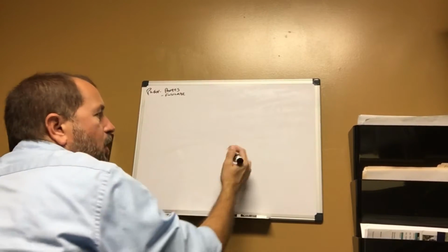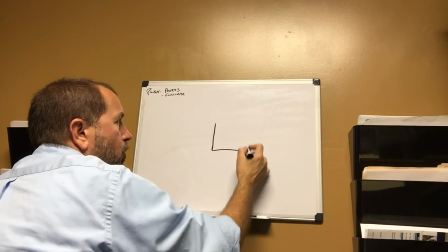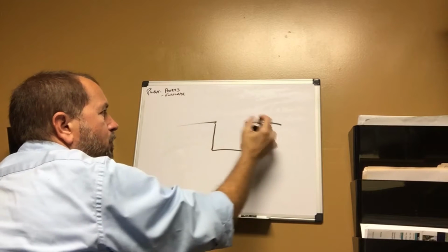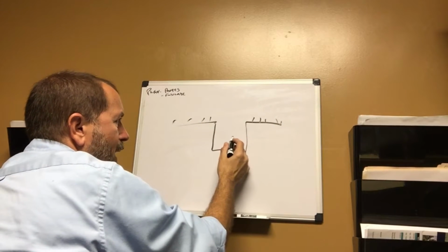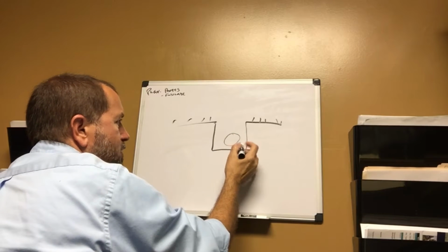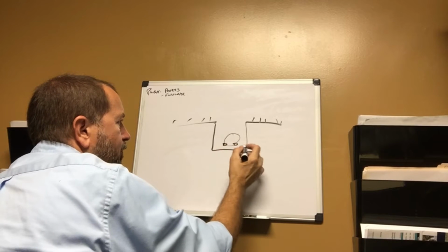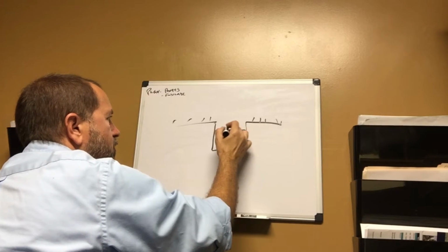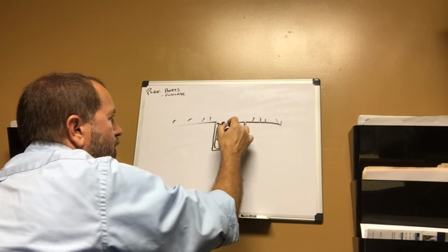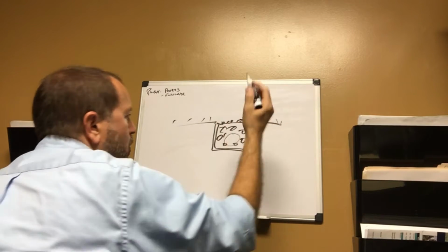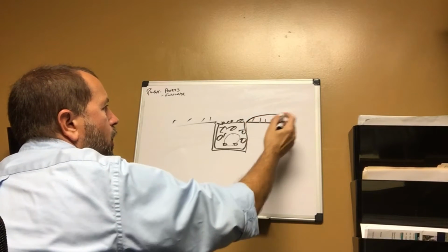A French drain is, we're digging this trench. We dig this trench in the ground like so. That's the ground. That's the grass. This is my hole. This is a pipe I put in the ground. The pipe has some holes in the bottom of it. And then I fill this thing up. It's all filled with rocks. It's filled with fabric going around it. It's filled with more rocks on top. So what's going to happen is the water's going to come off her mounded lawn like this.